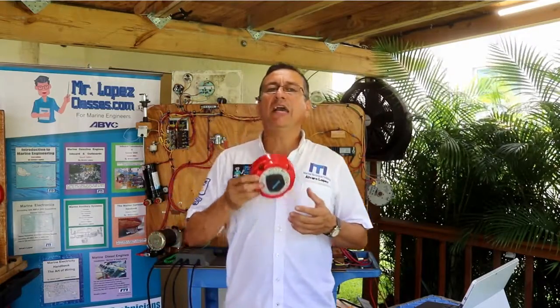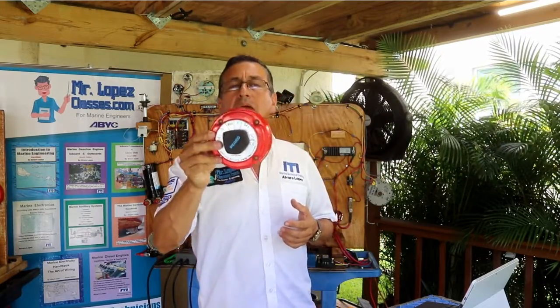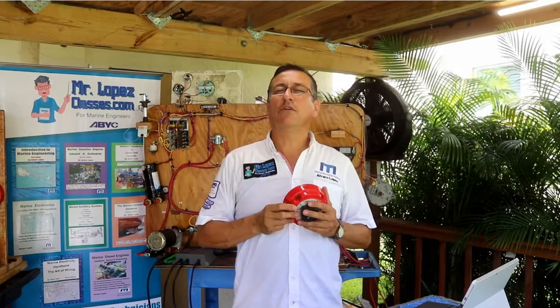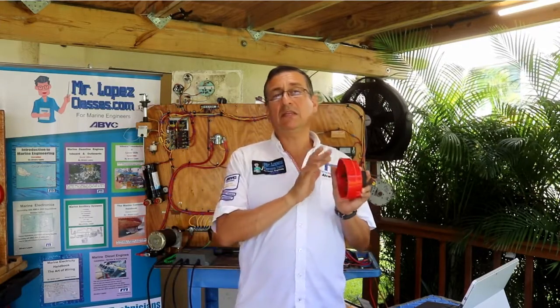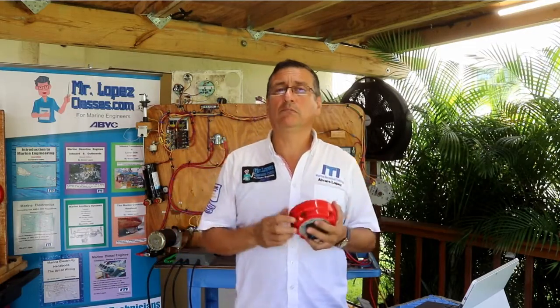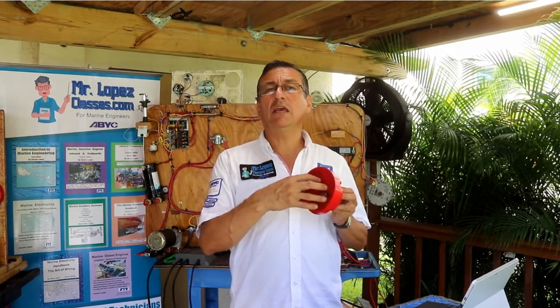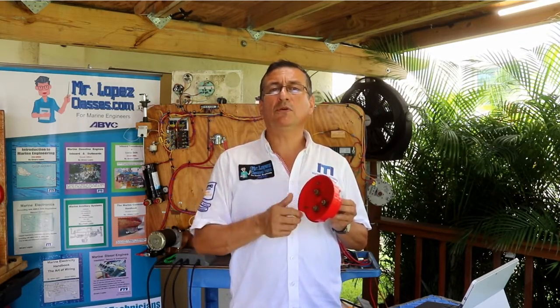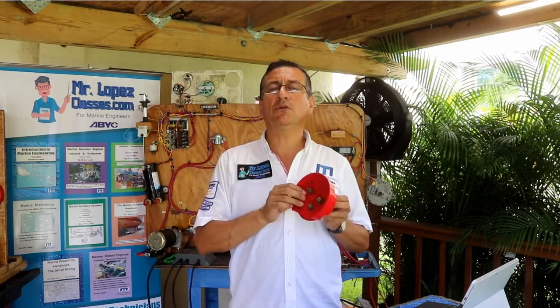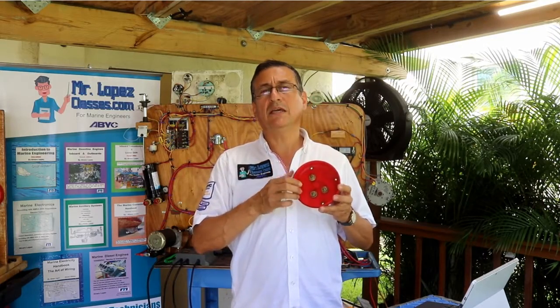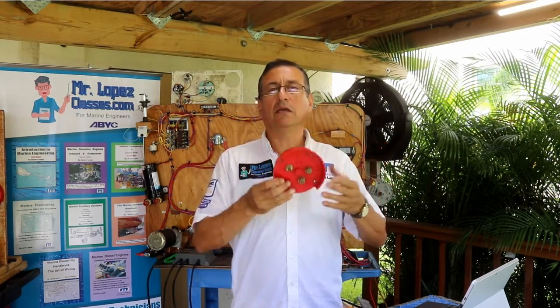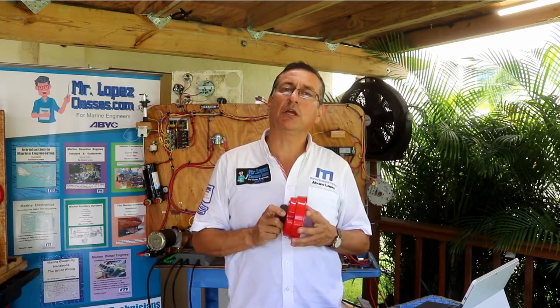What happens if I use my switch selector for a battery bank with higher capacity than the capacity of the battery switch? Simple. At any moment, internally it is broken, interrupted, because the high current increases the temperature and destroys the plastic and destroys the breaker, the switch, the battery switch selector.